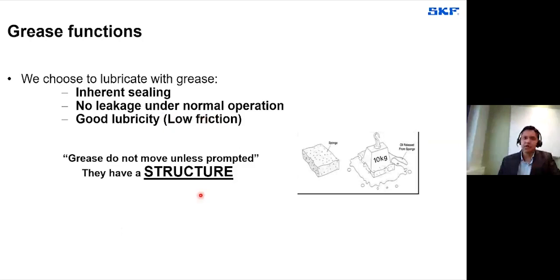The reason is that they have a structure. So grease does not move unless you prompt it to do so. If I take an analogy, I simply take a sponge dipped in water. If you take the sponge out of the water, then unless you press the sponge, water is not going to ooze out. Grease also functions in the same way. So here you need to apply certain forces, like maybe the shear forces, which normally occur in a bearing application.